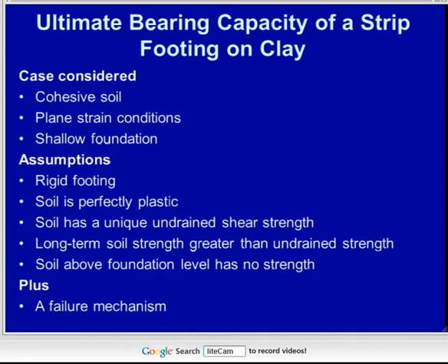But we never ever go into those trenches to work until we've got some sort of temporary shoring in place, because with time the soil's getting weaker, and if you left it long enough, those holes collapse. And so this uncertainty about what happens there with the softening leads to a safety-first approach, which is always use some sort of shoring protection. Don't always hold the sides of a trench up, but you normally create a box within which people can work, so if the trench does collapse, it's still safe.